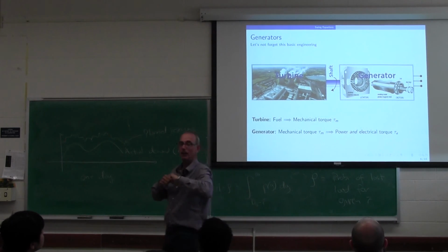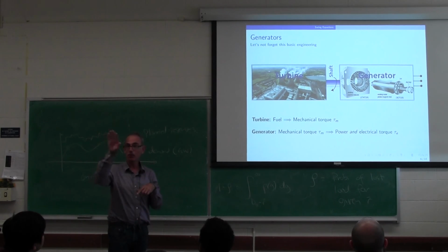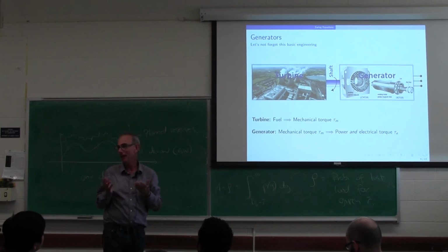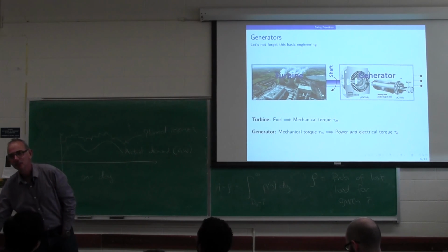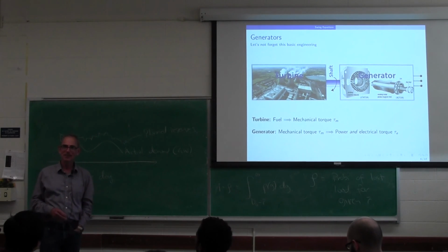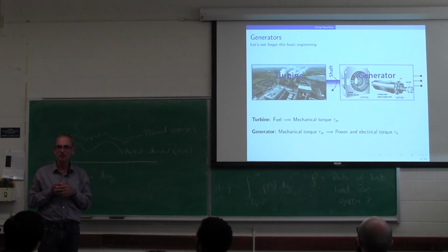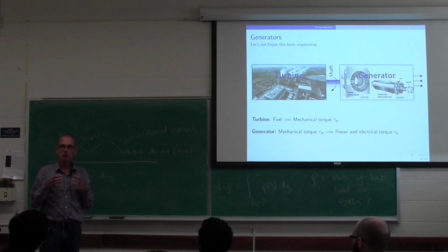In India and in Europe, they let the frequency go around a lot more than in the U.S. And in India, it's all over the place. There are blackouts, but it's not so much that. So there's another reason, which is amazing, which almost nobody, even power engineers, knows: the really high efficiency monster generators have all these fins in the turbines, these blades that have a resonant frequency. And to make them really efficient, they tend to have a resonant frequency which is close to some multiple of 60 hertz.